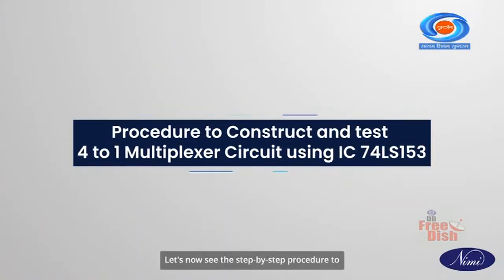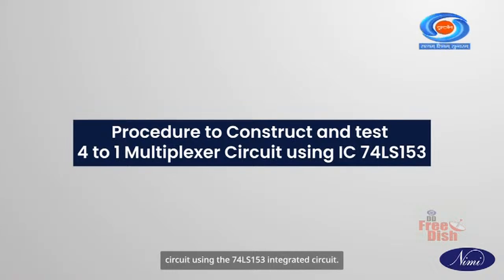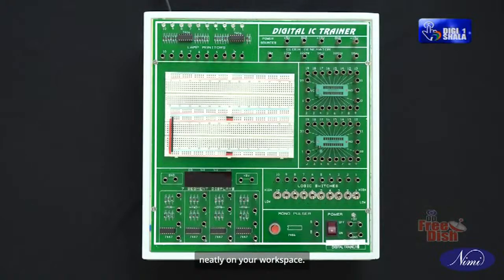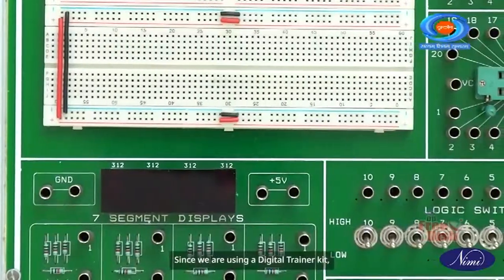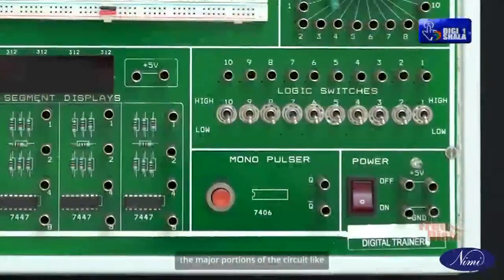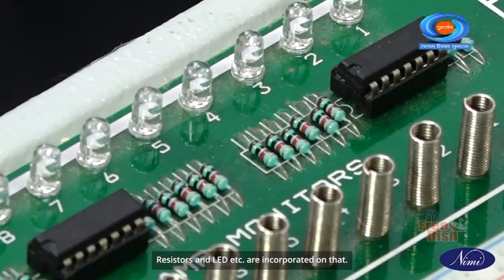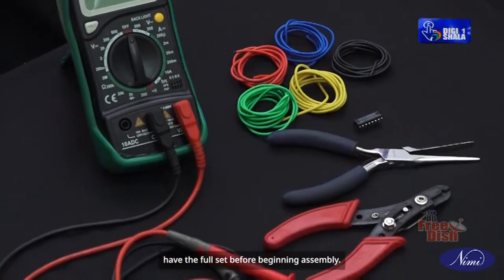Let's now see the step-by-step procedure to construct and test a 4-to-1 multiplexer circuit using the 74LS153 integrated circuit. The first step is to gather all your components, laying them out neatly on your workspace. This includes the 74LS153 IC. Since we are using a digital trainer kit, the major portions of the circuit like breadboard, power supply, switches, resistors and LED etc. are incorporated on that. Thoroughly inspect each part and verify you have the full set before beginning assembly.